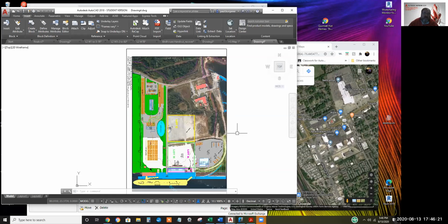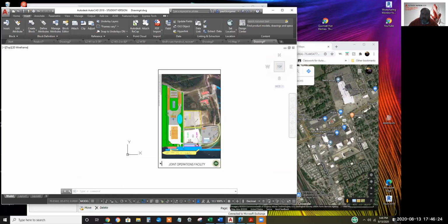Another use for images, I have a lot of gaskets and bicycle sprockets and lots of flat pieces that are scanned along with a tape measure in the scan, and you can scale that scanned image of the bicycle sprocket so the tape measure is accurate and heads-up digitize the sprocket. So it's kind of like a reverse engineering tool.